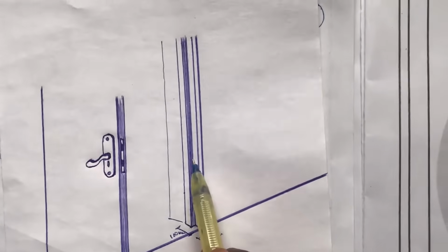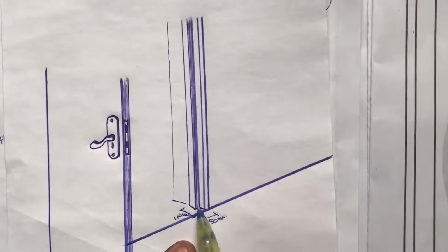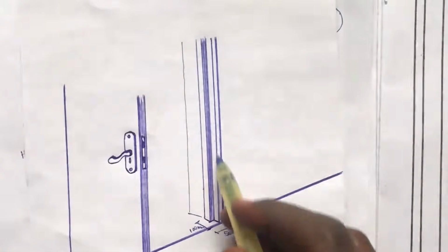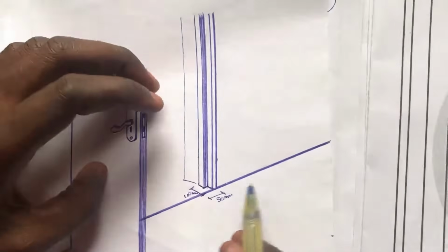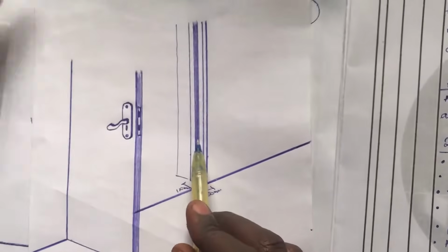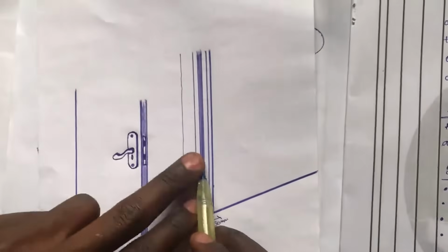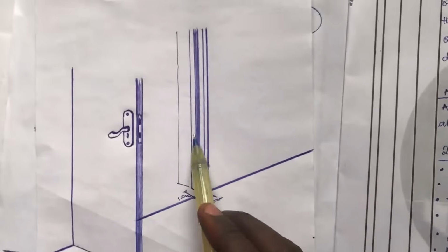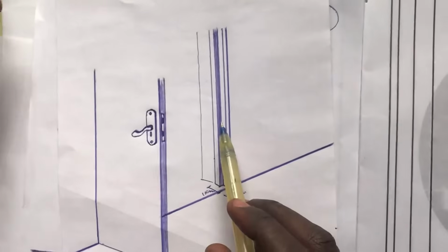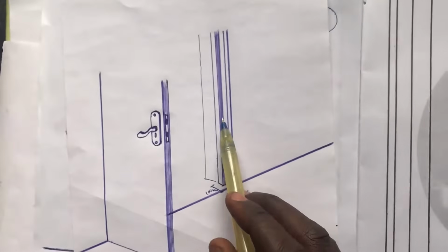Now this small space that I painted, this space that moves inside, is called a rebate. This rebate is mostly found on your framework, so that when you push your door it would not just exceed its limit, it would rest on this rebate. I think this is the best diagram I had for it. When your door rests on this rebate, it will not move into the building. So your door can just stop at this place.